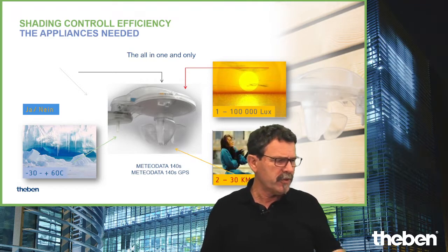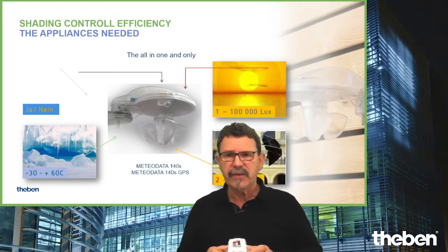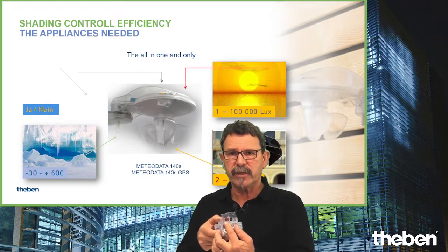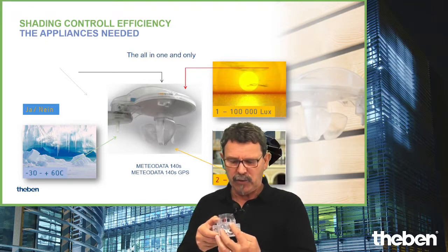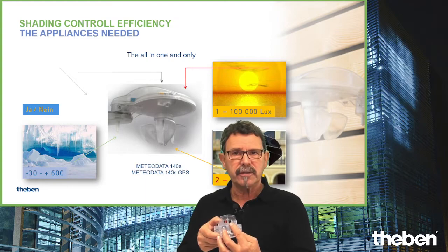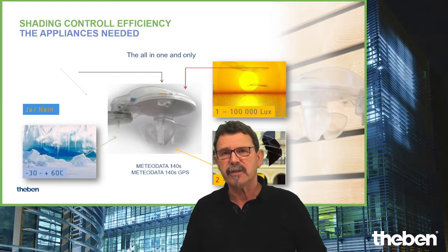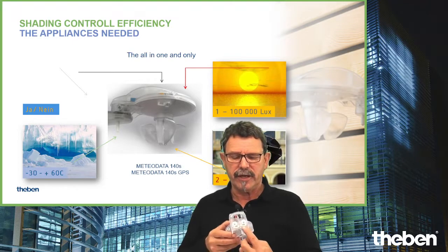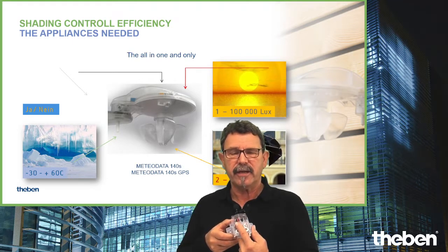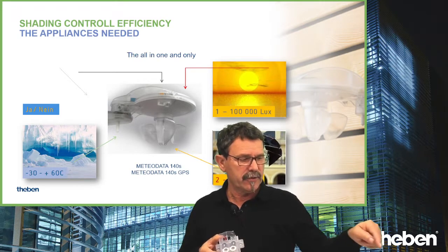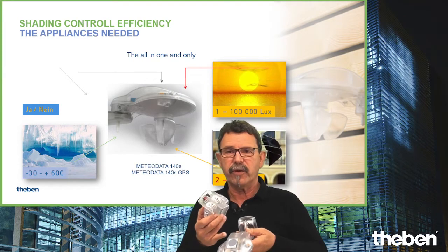So for that purpose you need to know that we do have here the bus communication, assuming you can see, yeah, and we do have here 24 volt DC. So that means the other 2 cables, the yellow and the white ones, you apply here, and the black and the red ones you apply here, and that's it. And with these 24 volts which you have to apply, you do the heating for the rain panel.